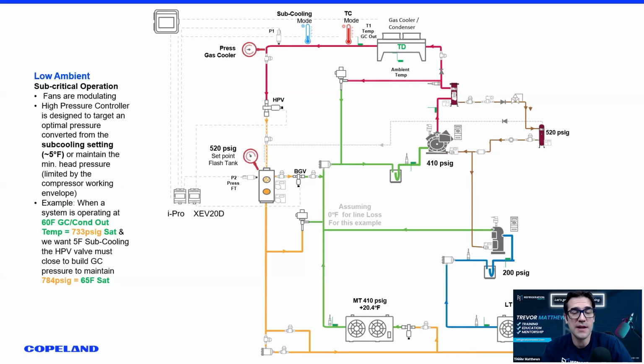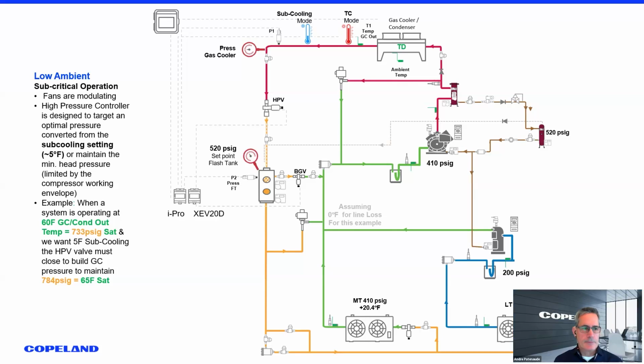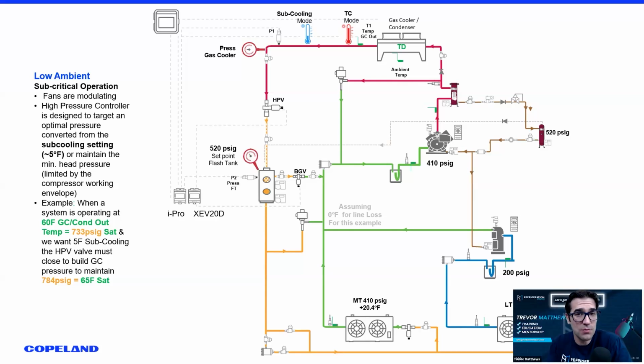And that's very important to understand, because this goes back to refrigeration 101. What's subcooling? What's superheat? Absolutely. And it doesn't change just because of CO2. Maybe it's working a little bit differently because we have a high pressure valve that's doing it, but that's the controller inside. And these are just set points that you will set up, which is great. Now it's super easy to set them up, and the controller takes care of it. You just have to check it and verify it with your gauges and temperature probes.